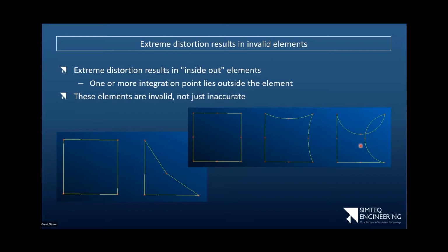Now this is something we get a lot when we try and project mid-nodes onto sharp radii and stuff. So it's entirely possible, even before something like this happens, if I bring these nodes closer together, I can get this edge to start overlapping with that one or this one as well. So again, the same kind of problem.